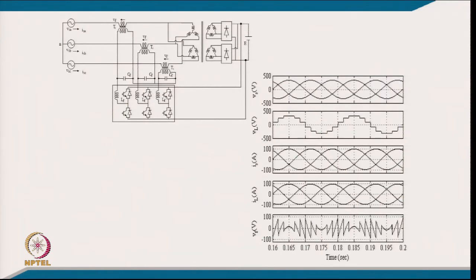So, this is the typical circuit here. The battery is not only connected across the load, but it is also connected in series with the series active filter on the DC link, and the DC link is common. With the help of the series active filter we inject a voltage in a manner that the currents become sinusoidal, balanced and in phase with the voltage. So, power factor is unity and harmonics are eliminated. Virtually, the series active filter is working to eliminate the current harmonics.